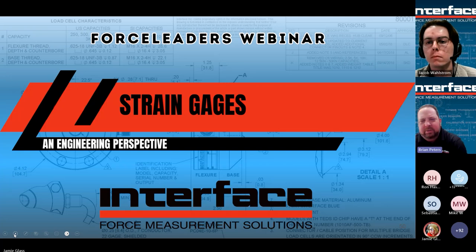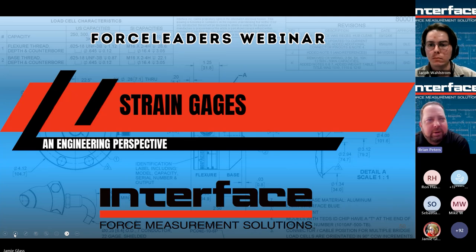Yeah, I just want to add real quick. All of our cables will support 6-wire. So even if the sensor is not a 6-wire or sense-enabled sensor, the cable will allow your instrumentation to actually read what that voltage drop is. And again, this all goes back to the fact that load cells are ratiometric, right? So that cal data is a function of 10-volt excitation or whatever the voltage is on that cal cert. And oftentimes customers don't realize that it's not quite getting what they think is getting to the sensor.